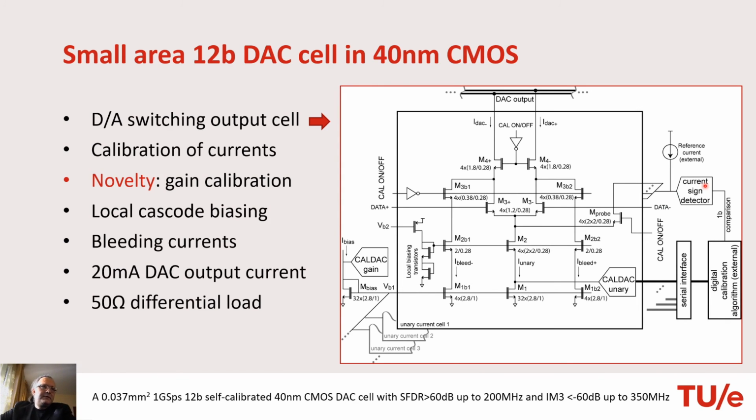Then this is read by the algorithm, and the calibration DAC word is updated according to the algorithm that I just discussed in the previous slide. And this is the output cascade. You see that all these transistors are actually thick oxide transistors. This is the requirement for the integration of the DAC unit inside the I/O bank.